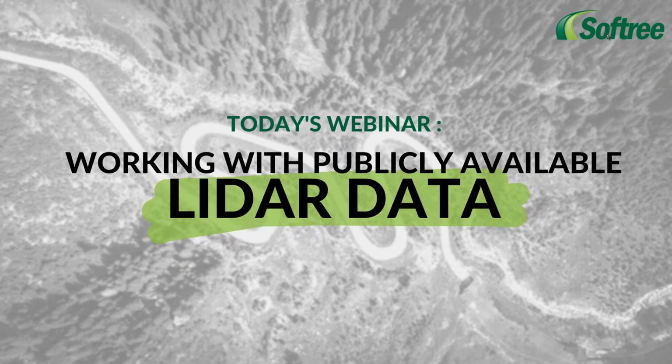We're excited to share this topic as we often come across clients unaware that their area of interest has LiDAR coverage through publicly available datasets. Working with public LiDAR can be a great tool for a couple reasons. It can be used for preliminary design, supplemental survey data, and if the quality is high and data is current, you'll be even able to use it for detailed design purposes.